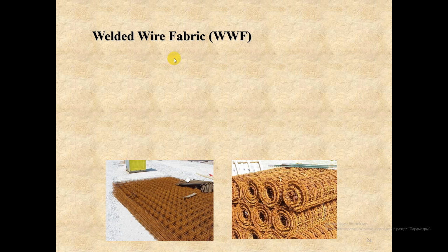The fabric is factory made by welding or interweaving wires complying with the requirements of building standard to form sheets with a length of 4.8 meters and a width of 2.4 meters, or rolls 48 meters and 72 meters long with a common width of 2.4 meters.